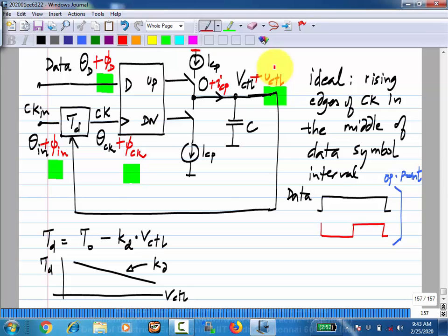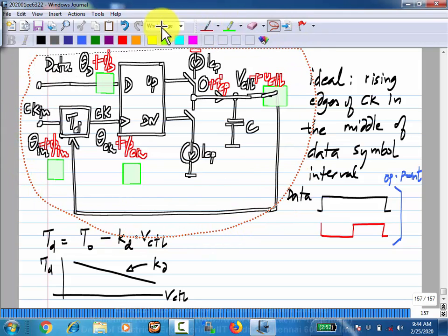So now I just have to represent the relationship. It's like what you do when you have a circuit with a transistor, a resistor, and a number of other components. When you have an increment in VGS and VDS, you have an increment in the current. That is represented by the small signal model of the transistor. Similarly for a resistor, a diode, etc. That's what we will do for every component here. We just want to find the relationship between the input and output increments.